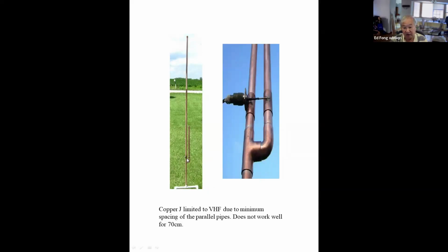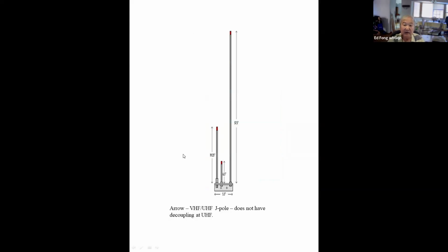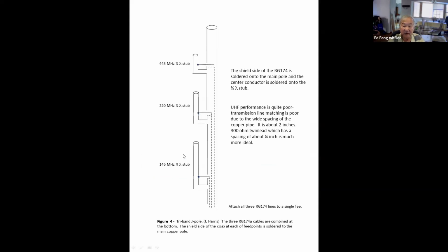So it's a version of this, except he sticks the coax in there since it's shielded, and it just taps it off. But he goes one step further. He says, that I get that working. If I want a 220 version, I step it up here. Here's a 220 version of a J pole, quarter wave at 220, half wave here at 220 left here.